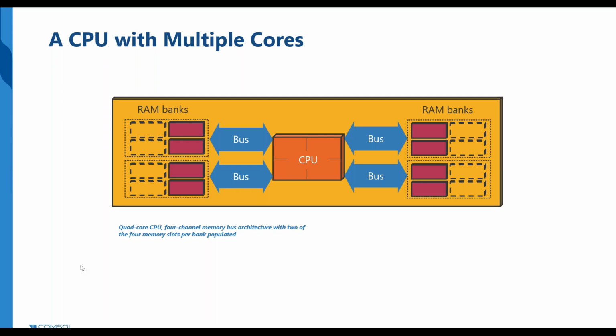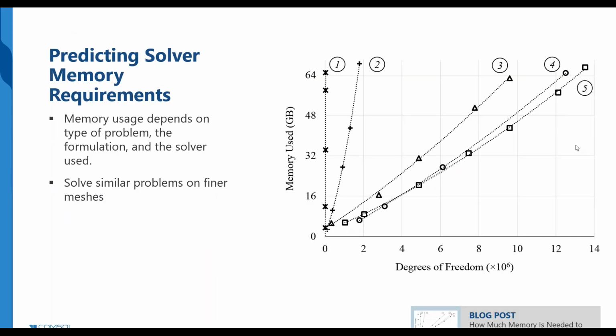And how can I be sure that my machine is able to solve the problem before starting the analysis? That you cannot be sure. I would not even be sure of that if you were giving me all the input data. You can do a qualified guesswork by, for instance, studying, as we did here initially, these types of graphs, by looking at trends, and you will have a behavior for your type of physics, for your formulation, and from the solver technology.